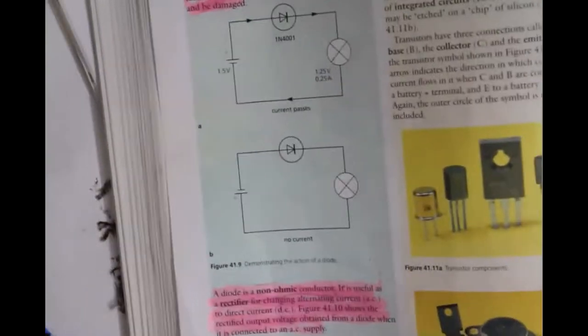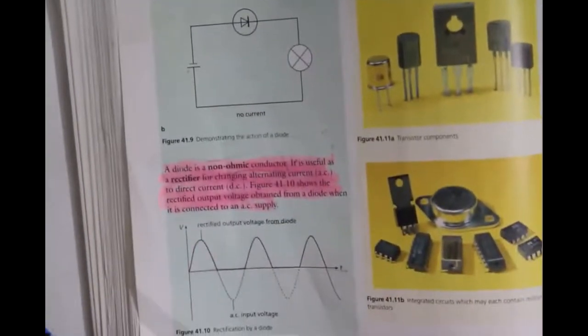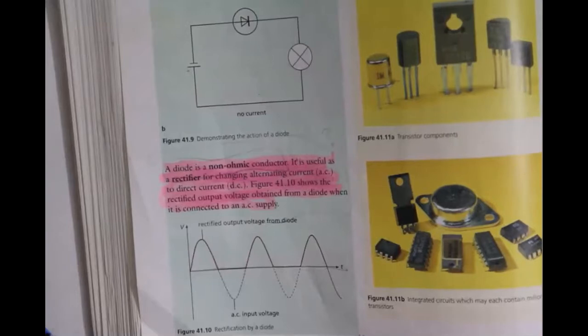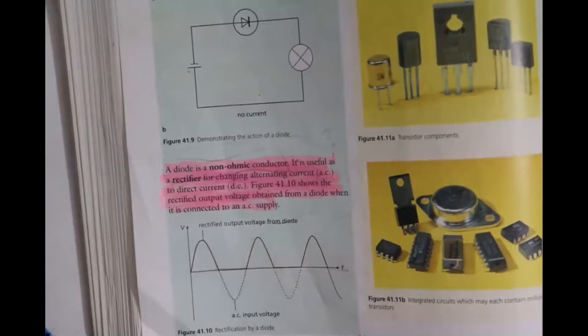And also appreciate that this graph is representing voltage and not current, and the magnitude of the voltage is increasing and decreasing. I mean, it is reaching zero and then reaching its peak and then reaching zero, but it is not getting negative. Meaning, what does that mean? That the current is not flowing in the reverse direction, because when it is trying to do that, the diode is stopping it. So that's what I said.